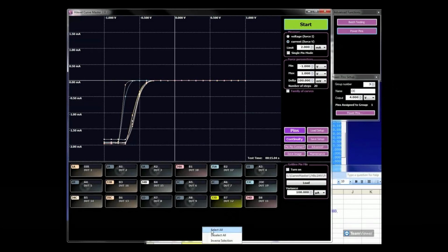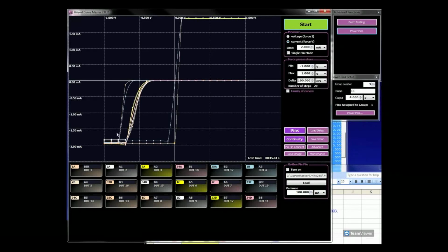This time, all of the pins have stopped at 0, except the 2 pins that we've applied voltage to. Why? Well, the output enable now disables all of the output buffers, preventing them from sinking or sourcing any current to the CurveMaster.